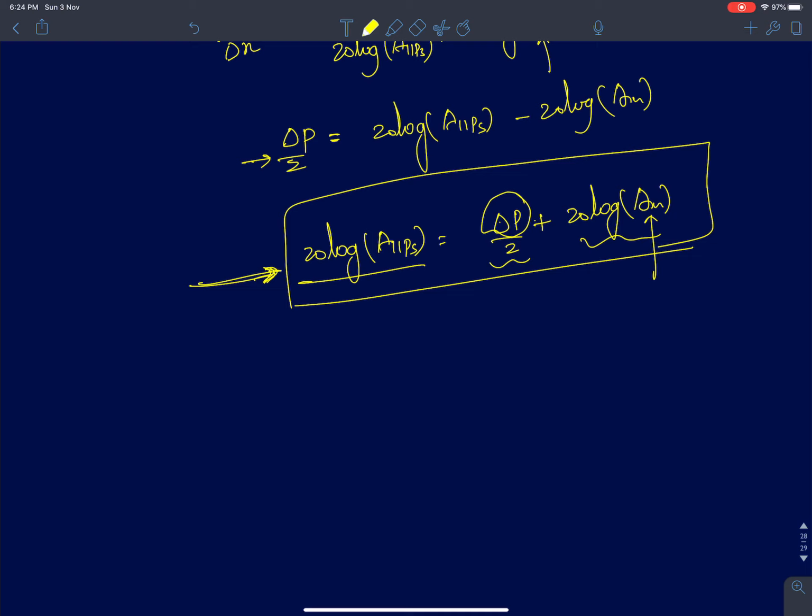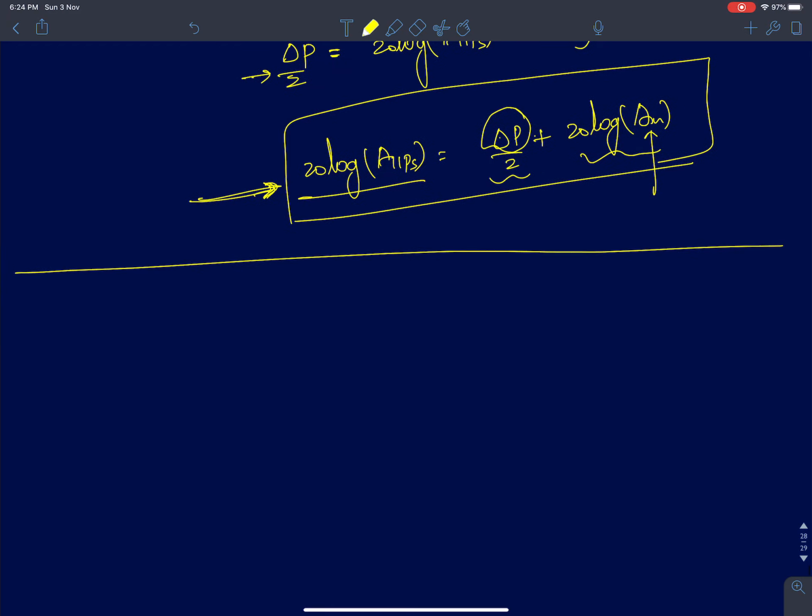Okay, so that's all about intermodulation. In this lecture I wanted to mainly introduce you to the idea of intermodulation. So what are the advantages of intermodulation? Why do we need a new parameter? The 1 dB compression point told you about gain desensitization. It told you what will happen if I have single interferers. Mainly, the 1 dB compression point tells you after what point you can no longer use it as an amplifier, because your gain will start compressing.